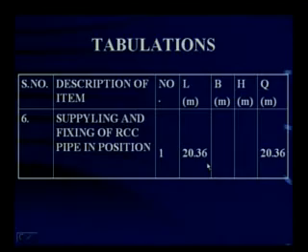There is only one item left in the detailed estimate of a pipe culvert, which you are eagerly waiting for. That is nothing but pitching with stones on upstream side, downstream side, and for the slopes. In this particular problem, you have seen the wing walls, is it not? I have substituted the wing walls for slopes. Is that okay? Calculation of the quantity required in a wing wall is very easy. Length, width into height. So I have not considered a wing wall in this particular case. I have considered a slope on all the 4 sides, one slope on each side. Is that okay?